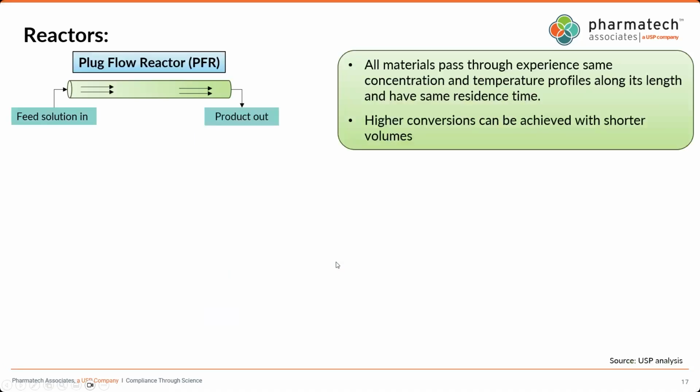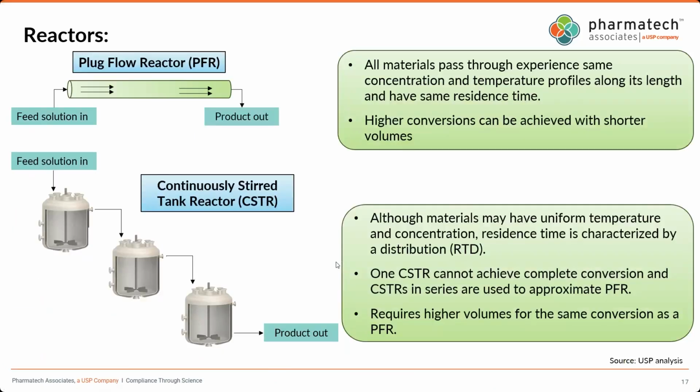The next important component in any continuous manufacturing is the reactors. Now, any engineer would be able to tell you there are three different types of reactors in this world: the batch reactor, the plug flow reactor, and the continuously stirred tank reactor. These are the very basic categories of the flow reactors. Out of these three, the PFRs and the CSTRs are considered continuous reactors. Now we know that an ideal PFR has no axial mixing, but perfect radial mixing.